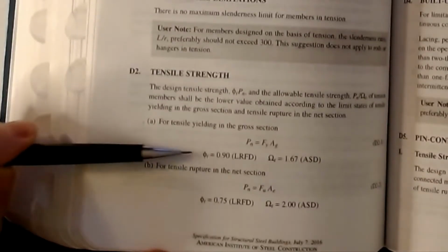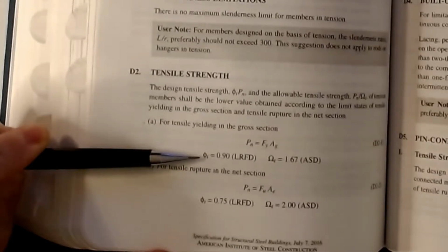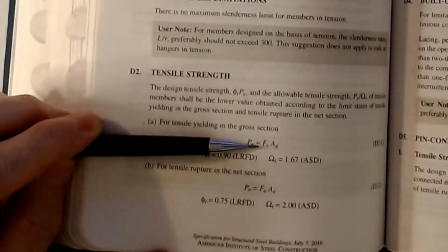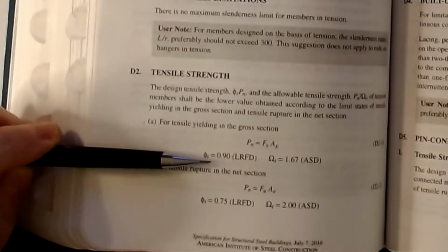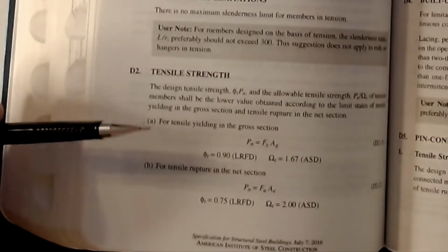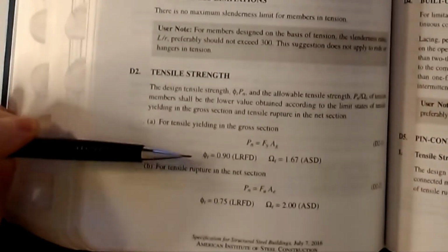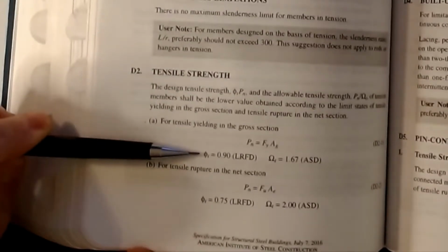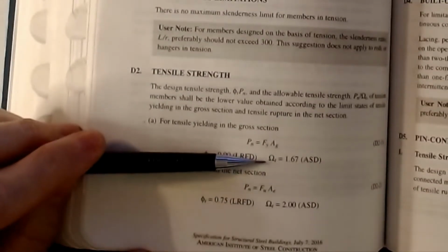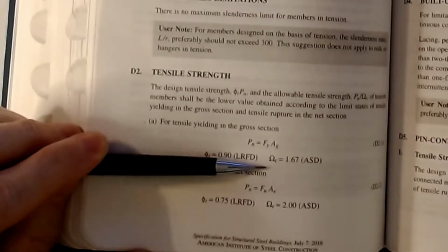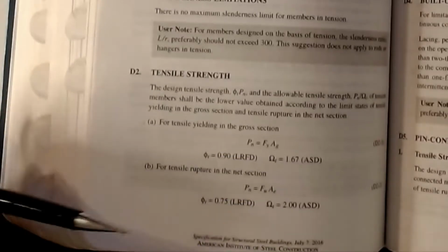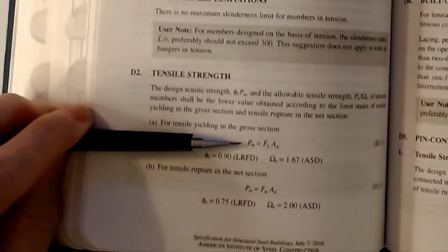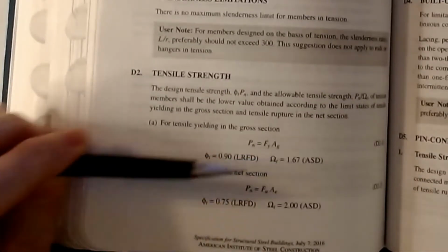Not always, but a lot of times if it's a yielding phenomenon, such as indicated by us using Fy here, then phi is going to be equal to 0.9 almost always. Again, there are exceptions, so make sure you look it up and get the right values, but for tension, that's absolutely the case. You can see that the ASD value is 1.67 for the yield criteria that we talked about in the last video. But again, we're not going to do anything with ASD in this particular book, but they do give you both. The equation works for both methodologies, they just change the factors accordingly.